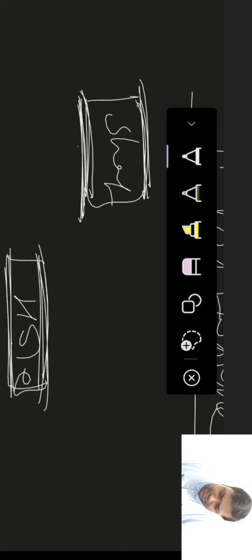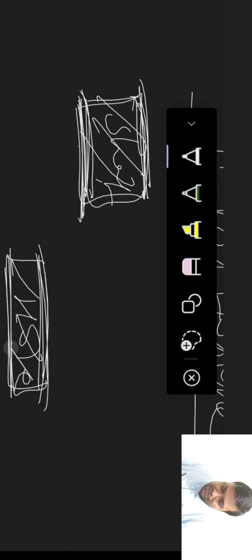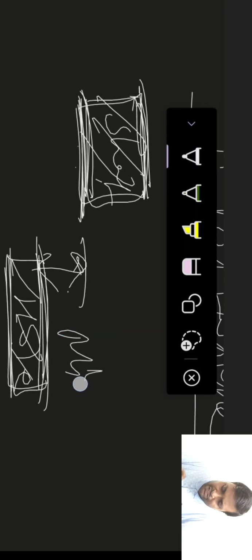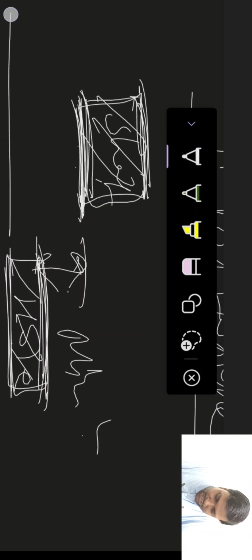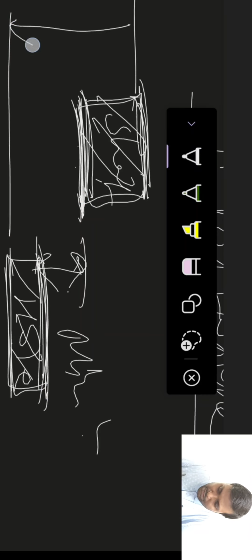This type of fit, when the shaft tolerance zone is above the hole tolerance zone, is known as an interference fit, and this value is known as minimum interference. Why is this minimum? Because the shaft is at minimum diameter, the minimum amount to interfere, and the hole is at maximum diameter. And this is known as maximum interference because the shaft is maximum and the hole is minimum.